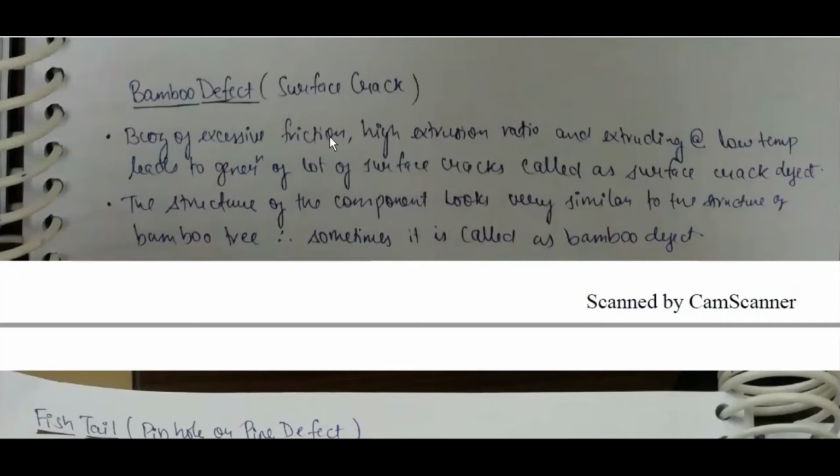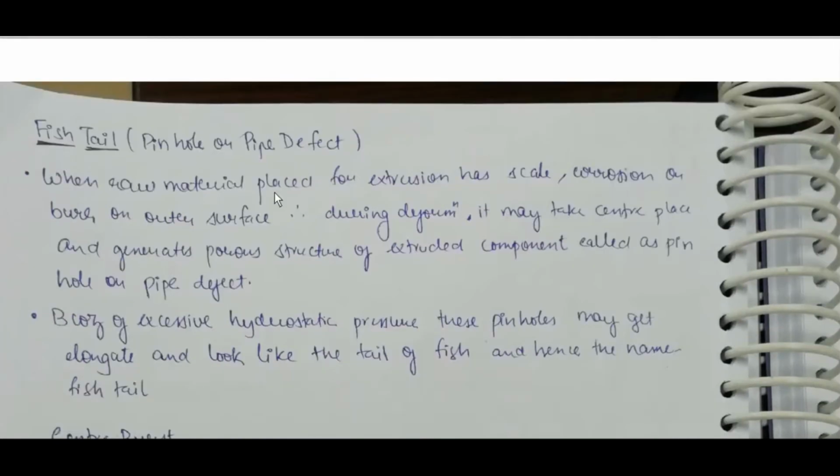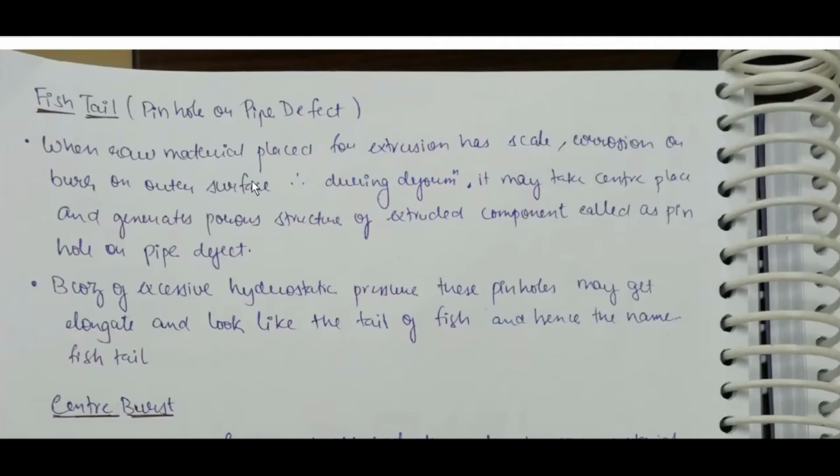Based on nature of force applied, press forging: when a gradually increasing load is applied for plastic deformation of raw material, it is called press forging operation. Drop forging: when a sudden impact load is applied for plastic deformation of raw material, it is called drop hammer forging.